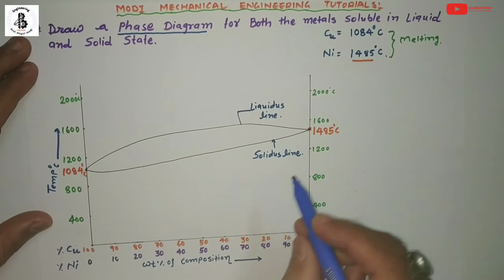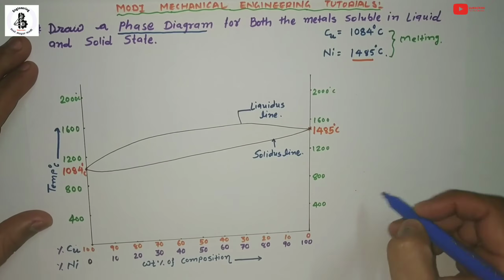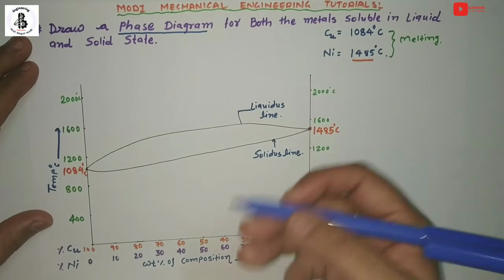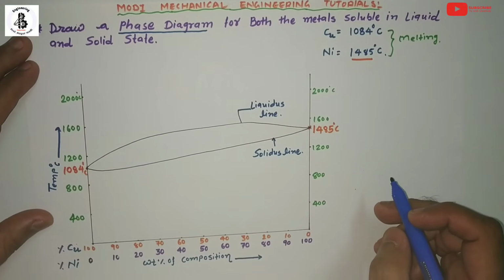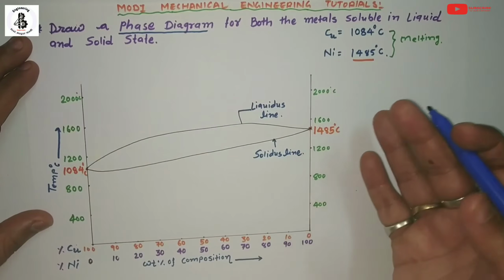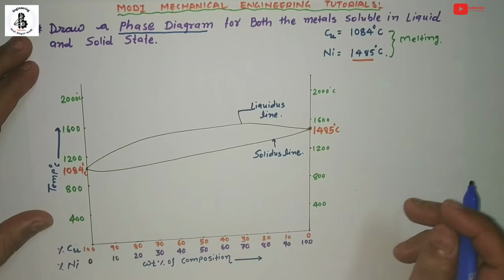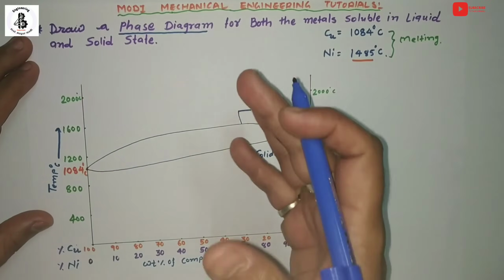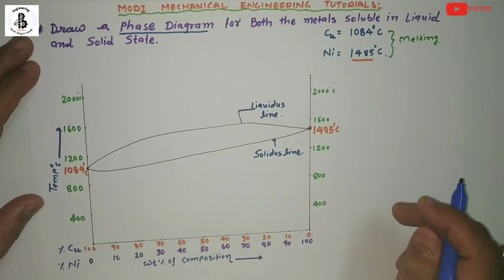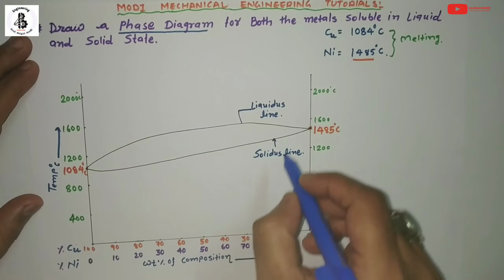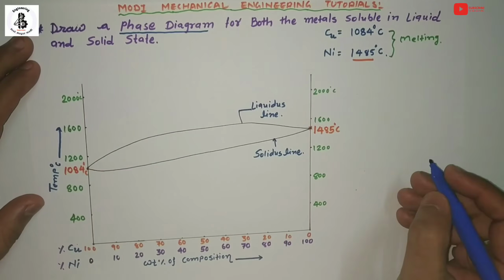Now from the copper-nickel diagram, you would also like to understand the lever arm rule, how to draw the cooling curves, the weight percentage of liquid and solid at various temperatures and compositions, how much percentage of liquid and solid there is in some cases, and a detailed introduction to the microstructure at the different stages of the phase diagram. So basically, this phase diagram helps in easily understanding the various phases that exist across the various compositions with respect to the various temperature conditions.